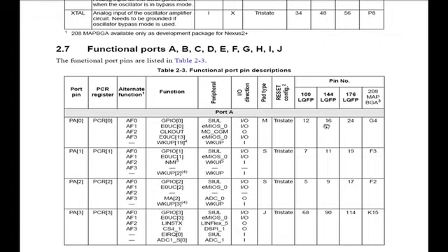And these are the actual pinouts, depending on whether you have a 100-pin or up to 228-ball package. Now, the register to configure the pin is shown here. It's just a number. For example, the pad configuration for port 0, or port A, pin 0 is pad configuration 0. If I want it to be a GPIO pin, then I will assign it alternate function 0. If I want it to be from the EMIOS and output, then it is alternate function 1, etc. And these are just binary values of 0, 1, 2, and 3 that we're going to load into that field.